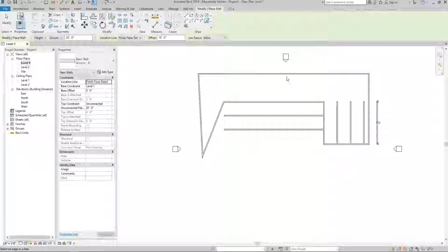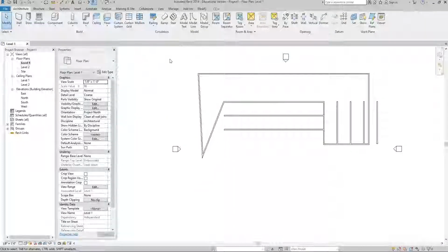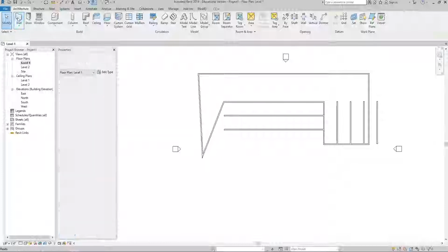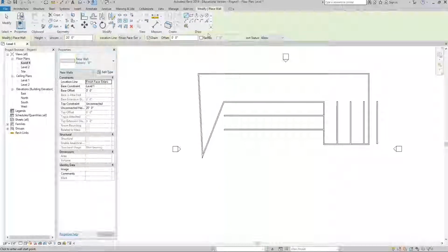Okay. So the pick tool, if I want to create a wall, I come up here, and again, this is just another way to generate geometry. I click on the pick, I give it an offset dimension, and there's really no other place you can specify the offset than here. So 2 foot 6 and 1/4 of an inch.